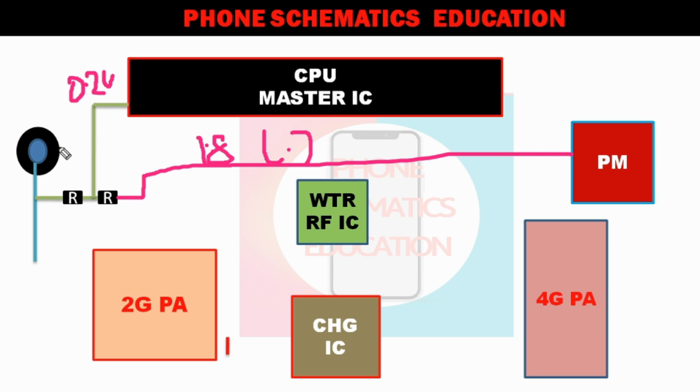For this you first check the RF cable and antenna socket. How to check the antenna socket? First you will get 3-point ground before connecting the RF cable, without battery. At your fourth point you will have a diode value of 300 to 500, right?